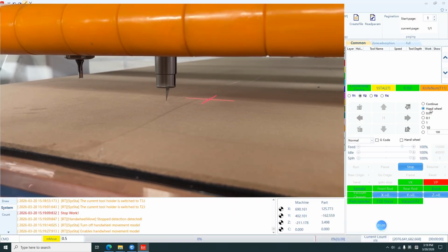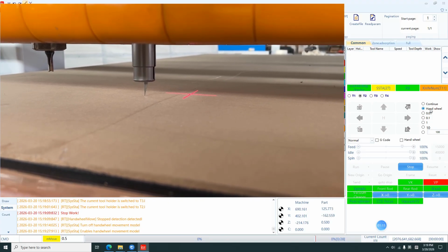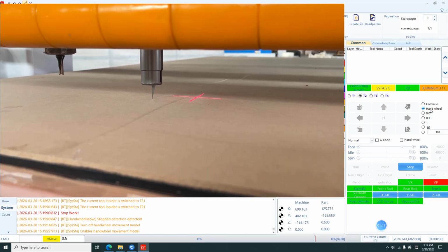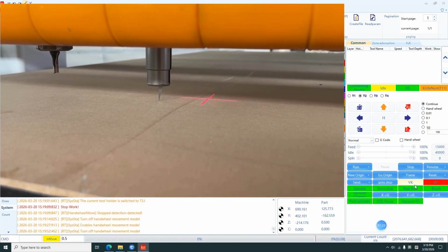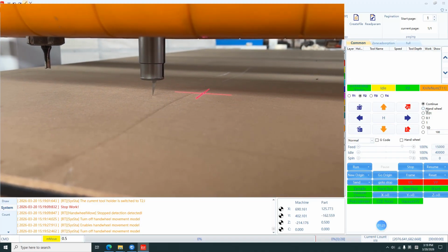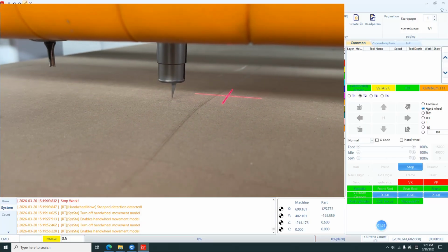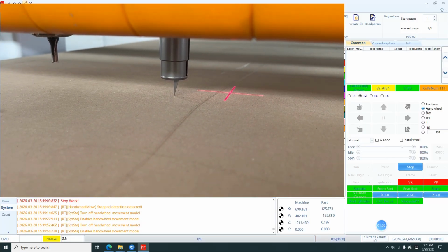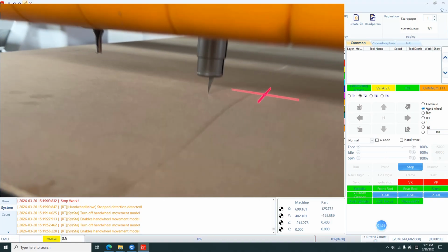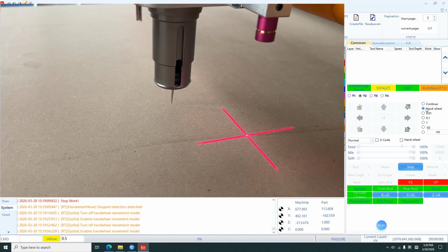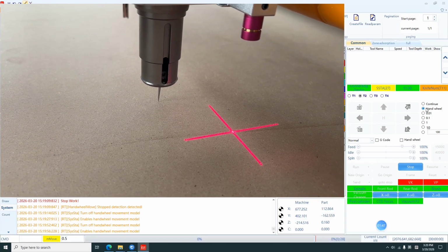Slowly lower the Z-axis, bringing the cutter tip close to the MDF board. Since the blade oscillates vertically, the oscillating knife function must be activated. Set the Z0 point while the blade is oscillating. In continuous mode, press the VK key to activate the vibrating knife. Ensure the knife tip cuts approximately 0.5 mm into the MDF board.